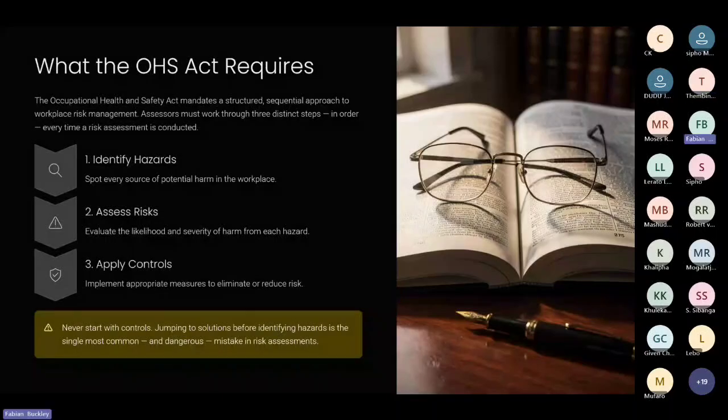So we sit around the table, we agree on what the activity is that needs to be done, and we understand the scope of work. We look at the area where the activity needs to be done. And then from that, we together compile the method statement, looking at the methodology, the people required to execute the work, the tools, as well as the material that needs to be utilized for that activity, and the plant and machinery if required.